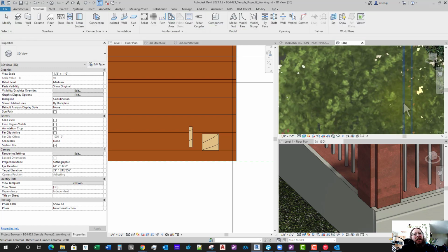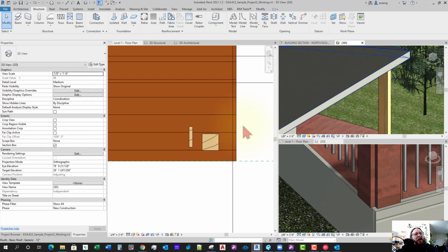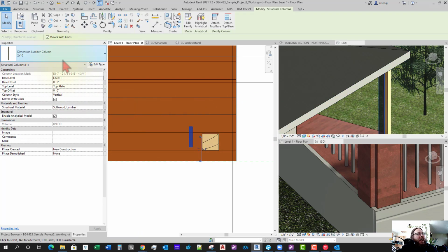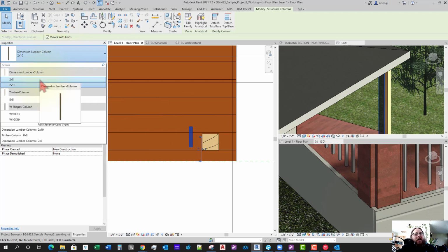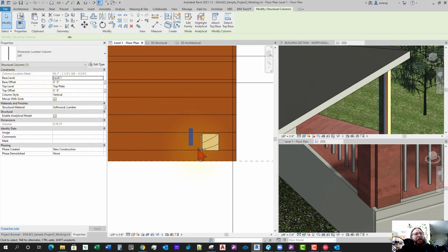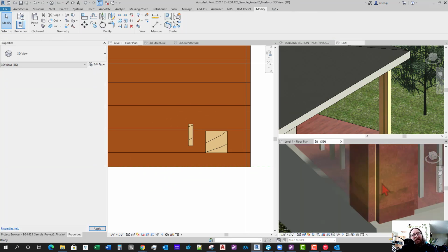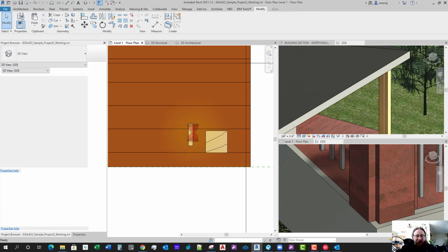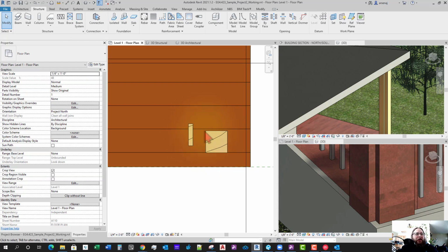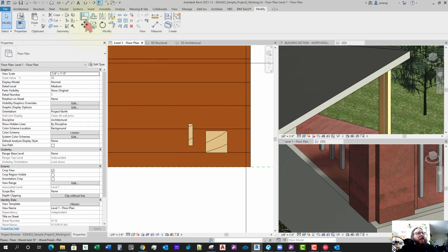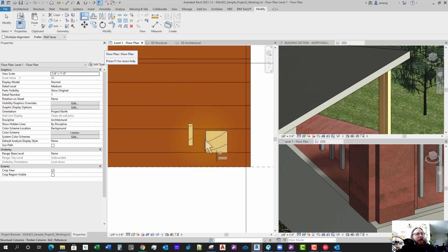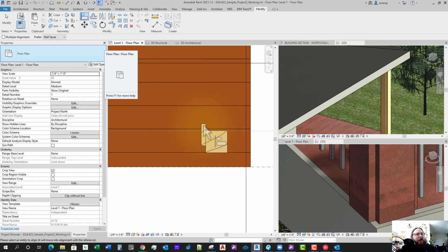Let's see. Oh, I'm stuck on the trees. So I think I might have used the 2x8. Yeah, that makes sense. Because if I have an 8x8 column, to get that look, basically they would attach these columns to the face to give a notched corner. So I'm going to go to modify, hit align, and align these columns to the face here.